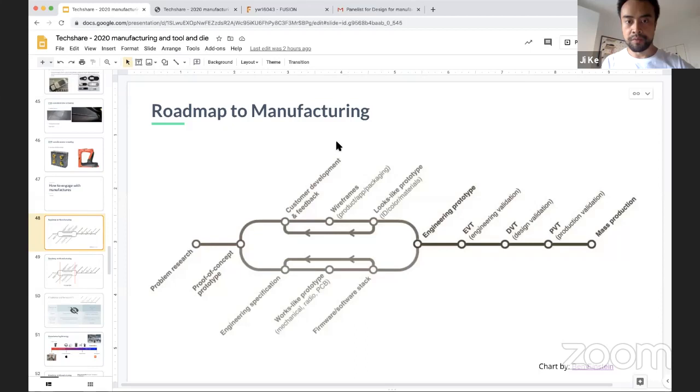Do early stage consumer products optimize for molding cost during design? Yes, you do. So the first thing you want to decide is what kind of manufacturing method to go with. Should you go with sheet metal, or a plastic body? And if plastic, based on the volume you're working on, do you want injection molding, or something like vacuum casting, or even 3D printing?